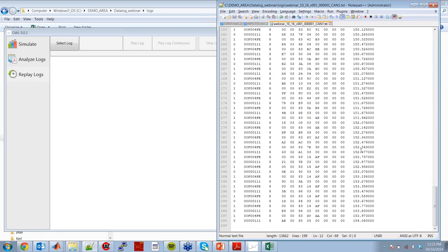The display model's already parsing the CAN messages using the DBCs, and there are engineering values like engine speed and RPM on the bus in Simulink, so it's a simple matter to send that directly out to the USB stick and put it into a file there, and avoid the need to work with the raw CAN logs. People usually do that if they want to implement a freeze frame or something on the logger.